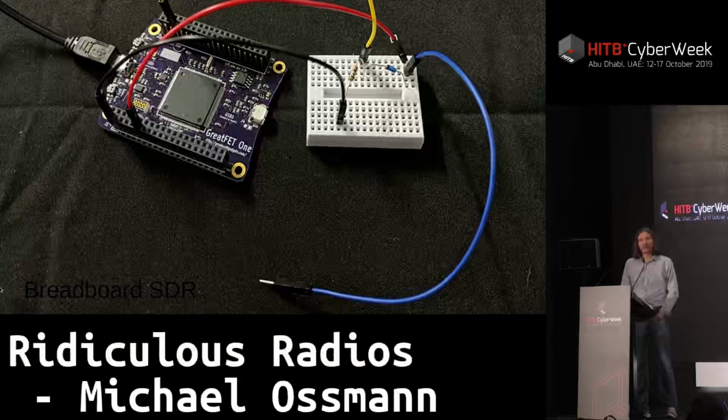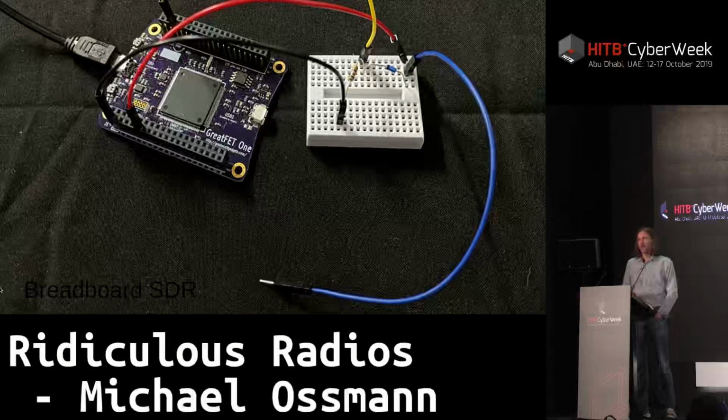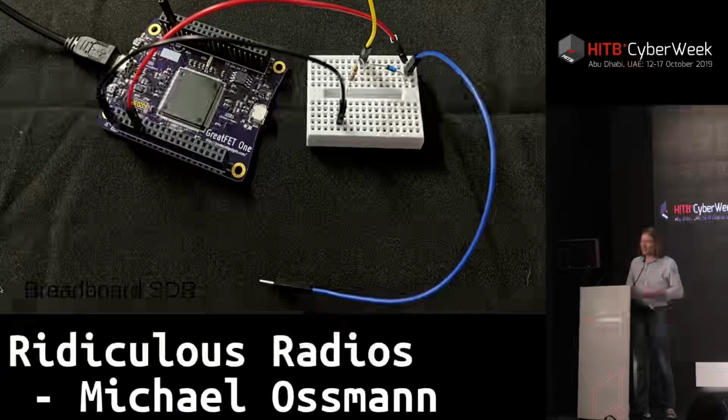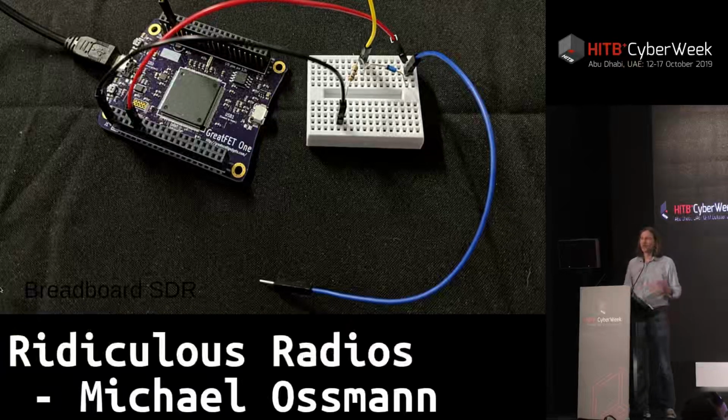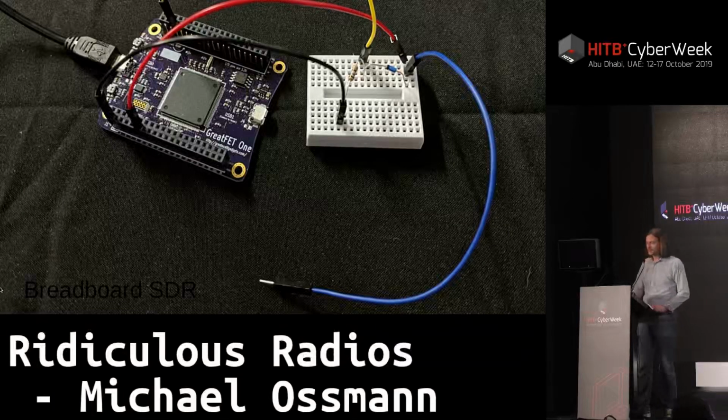It kind of goes to show that there's a lot to know about antennas if you want to make an optimal antenna. But if you want to make a functional antenna that isn't really optimal, you don't need to know a lot. You don't need to tune very precisely. You can use any old piece of wire, and it'll probably work over some distance. It just may not be as great a distance as, in theory, it could be with a better antenna.